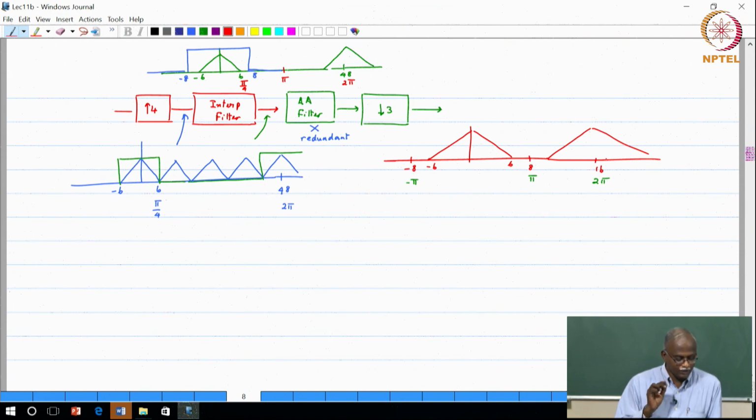Okay, let me write this one in green, and in red let us write the 16 kilohertz, okay, which is exactly what we wanted. So, the two things to remember: always keep the interpolation or upsampling with the corresponding filter, because those two go hand in hand in the sampling rate conversion process. Even if it is just an integer sampling rate conversion, we prefer to look at it not just as inserting 0 valued samples, we would like to look at it as insertion of 0 valued samples followed by filtering, so that you get the interpolated signal.